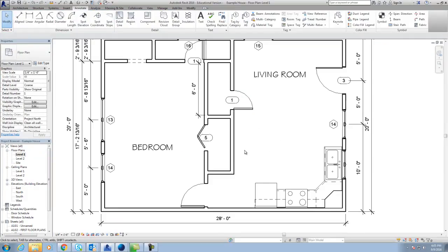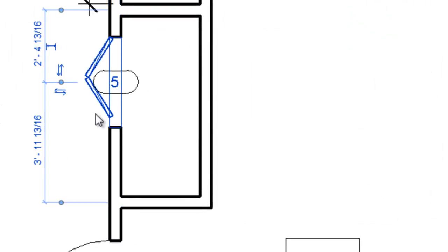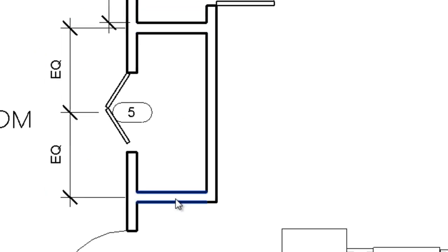And looks good. And I want to center this door up. All you have to do is you can actually click this little fella. Whenever you click on it, it puts these temporary dimensions on. That makes it permanent. You can click on it again. There's an equal sign right there. It'll put it right in the center. So you can put your rod space across.